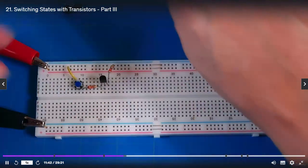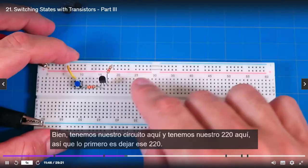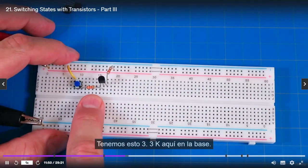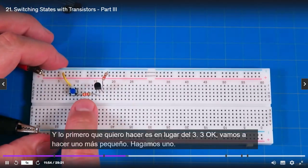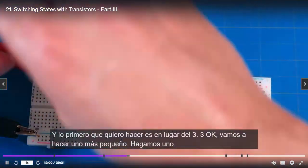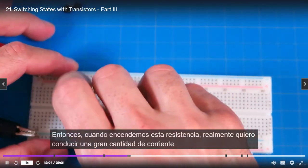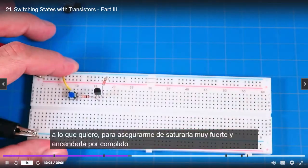All right, so we've got our circuit here, and we've got our 220 up here. First thing is, let's leave that 220. We've got this 3.3K here in the base. Instead of the 3.3K, let's use a smaller one, a 1K. When we turn this transistor on, I really want to drive a lot of current into it. I want to make sure I saturate it really hard and turn it completely on.